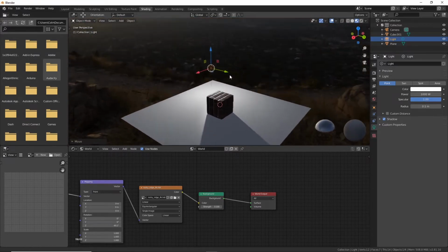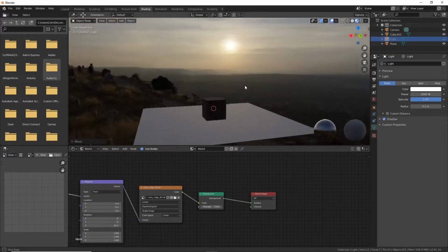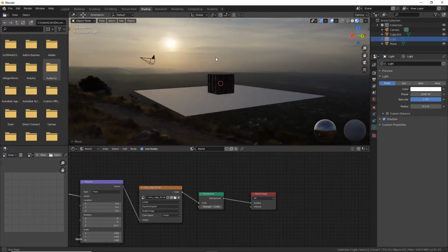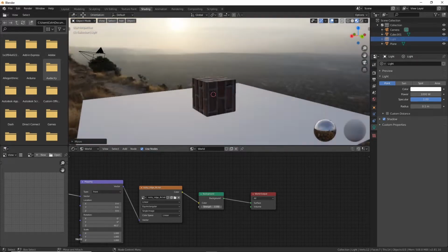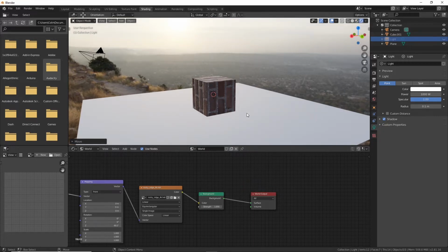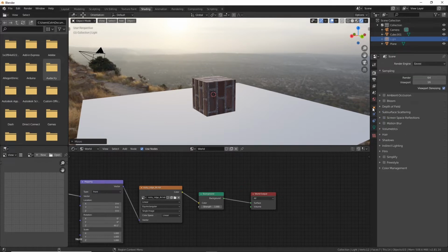Right? So if I turn that light off, now it's off, and you'll get some shadows from this environment, but because I've set it so low on the render, it's not going to show. And really, for an HDR image, the shadows won't cast in real time. You'll have to show them in rendered mode, and it has to be in an alternate render engine called Cycles. Let's just check to make sure. Shadows. Yeah, it's not.